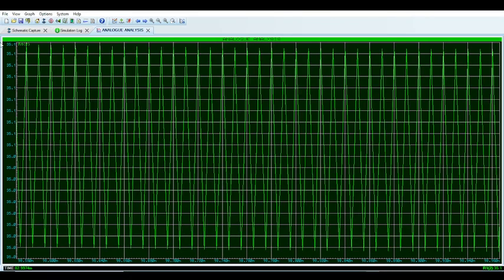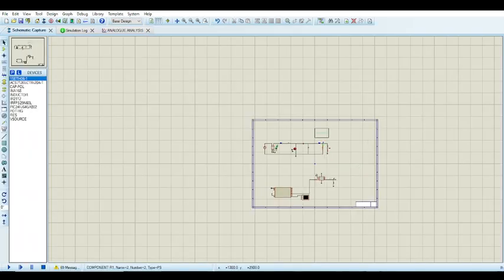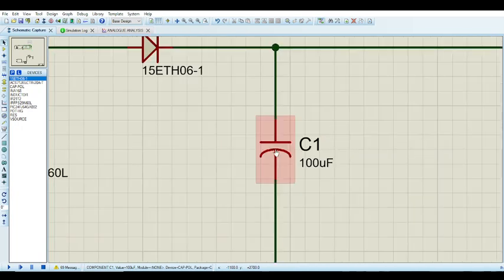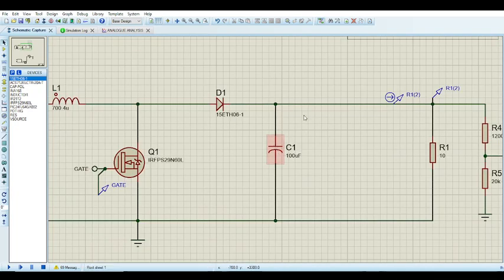And with average current mode control, especially when we're dealing with fast loop times, you don't want your capacitor to be too large. Try to keep it low, because when you actually calculate the capacitance required, it's usually not large. It's about 3 microfarads or something like that, or 5 microfarads if it's quite high.